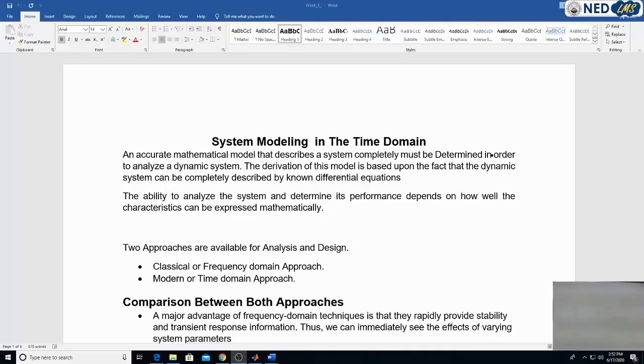In the previous lectures, we have studied system modeling technique in frequency domain. For system modeling, you want to represent a system, and you started representing a system in frequency domain with the help of transfer function. Transfer function basically characterizes the dynamics of the system in S domain or frequency domain. Similarly, you started analyzing the system response by the technique named Laplace transform. Laplace transform provides the mathematical tool to analyze that S domain transfer function.